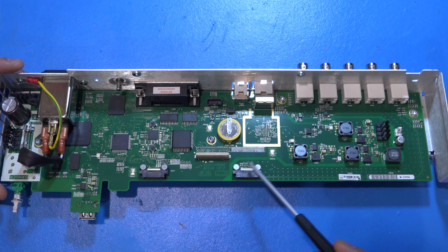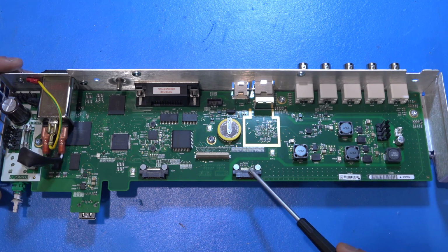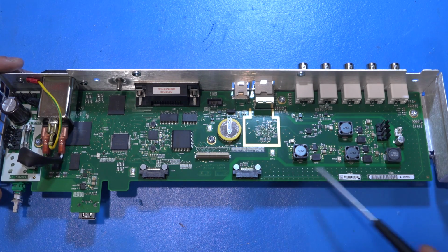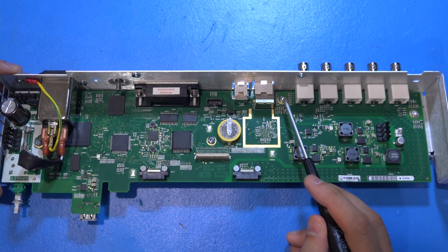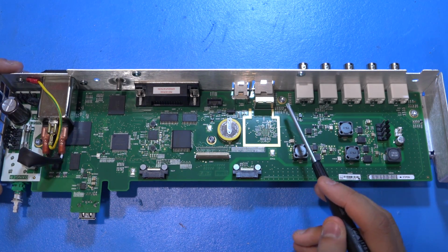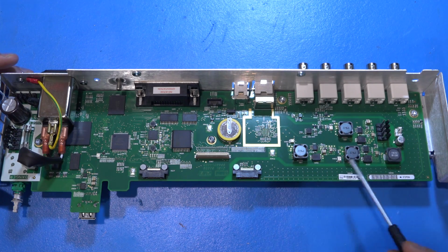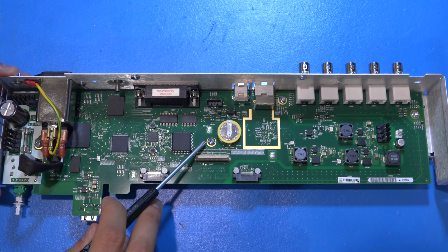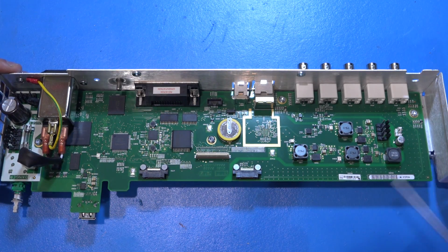If you look carefully through the PCB layout, you can see that this is all isolated, and that's because this goes directly through here to the analog board. This is still essentially part of that analog board, and that's why if you look carefully here, you can see a similar grounding, handling the ground connection just in a similar way, because this is still part of this part of the board. Whereas with these guys, you don't need anything like that, because this ground is nowhere near as critical. It's the interface between this ground, you can see another one over here, with respect to the rest of the system. Very nice, and tons of work must have been going into designing that.